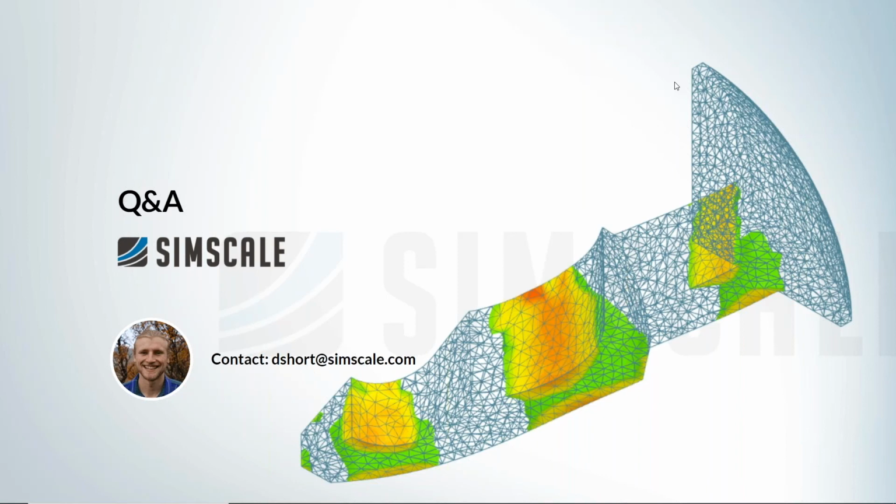So you could do both, to be honest. But second order elements are much more efficient because they can resolve in the displacement, in the deformation, a quadratic function with a single element. And if you think about a first order element where the shape functions are just linear, you're going to need at least 5 elements to have some kind of good representation of a parabola or quadratic displacement relationship. So if you go with first order elements, you're going to need lots and lots of very small elements to get the same results as you would get with a fairly coarse second order mesh.